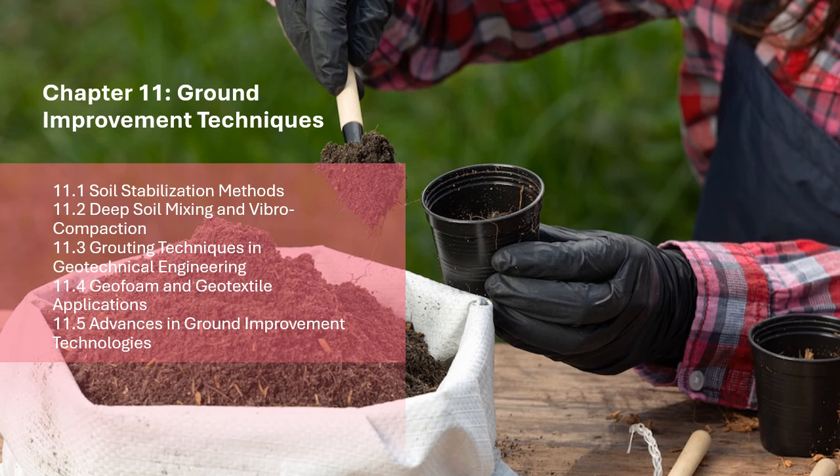3. Drainage and filtration. Geotextiles are highly effective in drainage applications where water flow needs to be controlled or directed. They act as a filter, allowing water to pass through while preventing soil particles from being carried away, thus maintaining the integrity of the soil structure. Example: geotextiles are used in the construction of French drains, stormwater management systems, and retaining walls to facilitate water drainage and prevent soil erosion.